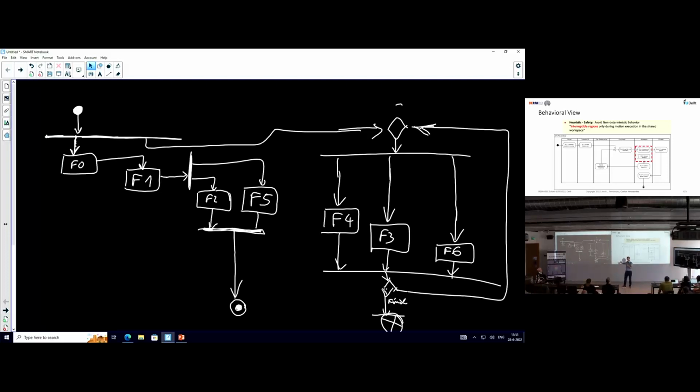In the other part, at the back, the robot was moving in a perfectly defined environment where the human could not reach. So we could use predefined motions there. But while it was interacting or moving in the part next to the human, we allowed the skin to interrupt the motion. So we limit the interruptibility region, not to the entire diagram, but only to this part. And this simplifies, or guarantees, the design in the rest of the system.